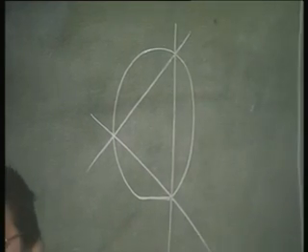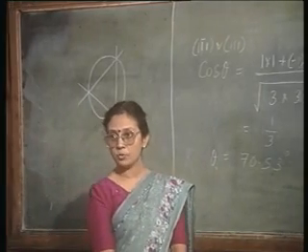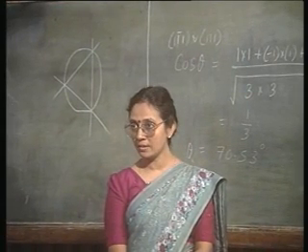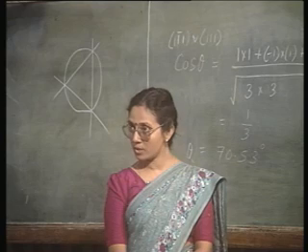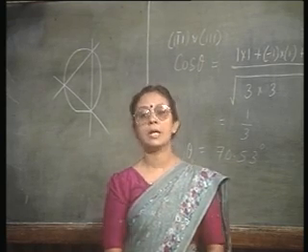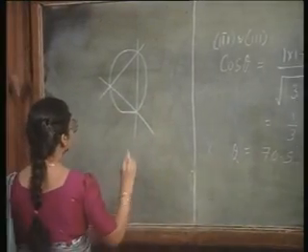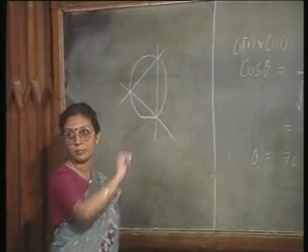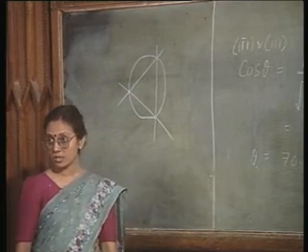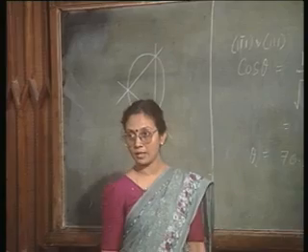Remember, the 111 plane, it is bound by the 3 110 lines, and they are constituting a triangle, and the angle between any two 110 lines is not 90 degrees, but 60 degrees, right. It is an isosceles, sorry, it is an equilateral triangle.